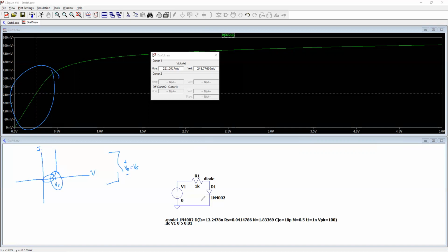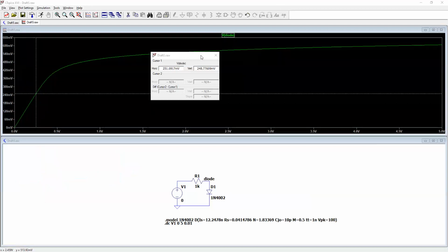So once that happens, then we're going to see the voltage for the diode kind of level off. And it's not going to be perfect because this is trying to simulate more real life scenario. So it's going to slowly increase. And if we had a much higher voltage applied, we would see it kind of level off around 0.7 volts. But since we're looking at a lower voltage, we're going to see it level off around 0.5, 0.6 volts. Okay. Get out of annotation mode here.